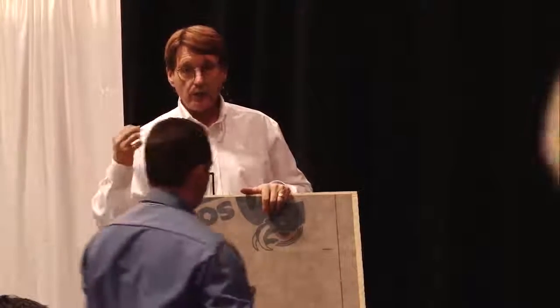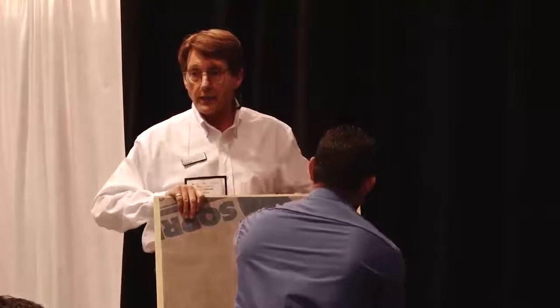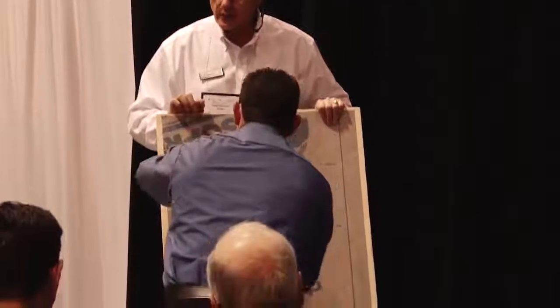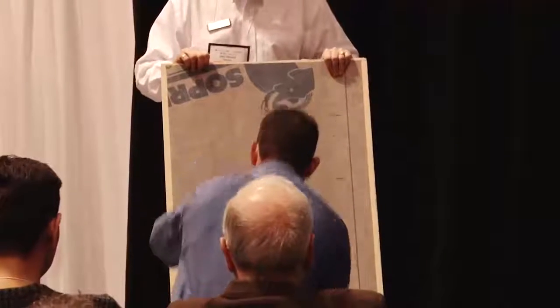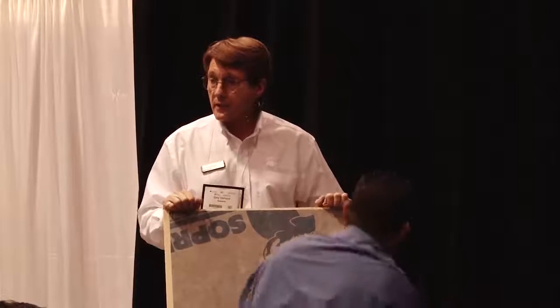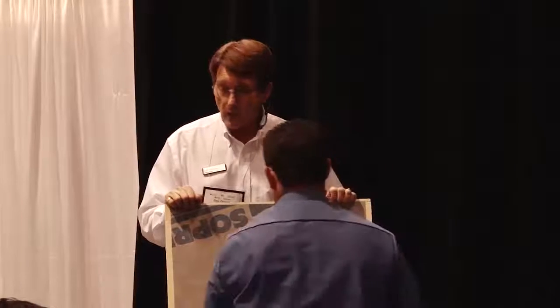The next, very critical issue of all membranes used in air barrier technology is that they need to be rolled, whether this is an SBS modified membrane or the new PSAs. We refer to all of them needing the pressure. This is a PSA, pressure sensitive adhesive, whereas with the Sopraseal Stick 1100, the black on the back, that's a pressure sensitive membrane. You use a primer. The primer leaves residue on the substrate as the water or solvents evaporate, and then the membrane sticks to the primer itself.